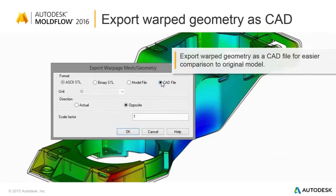This is another one that I think is going to be super useful. If you brought in your CAD model as a CAD solid model and you run a warpage analysis on it, we can now use the deformed mesh from, let's say, your dual domain or your 3D model, the warp mesh, to morph the original CAD model so that it complies with the deformed shape.